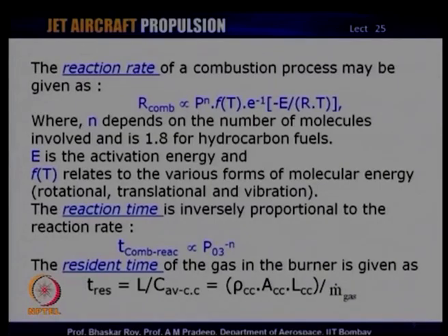The reaction time is decided primarily or directly proportional to the pressure that is available, and hence we have argued that it is necessary that you allow air to go inside the combustion chamber with as high pressure as possible to impact on the reaction time, which, as we just mentioned, is related to the fastness of the burning process, and then the resident time, which is related to the average combustion chamber density, the flow inside the combustion chamber, the area, the length of the combustion chamber, and then the mass flow through the combustion chamber.